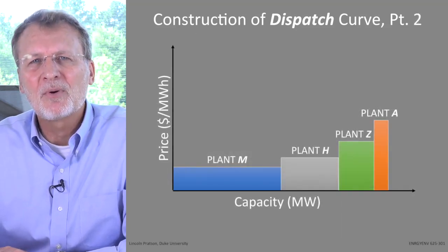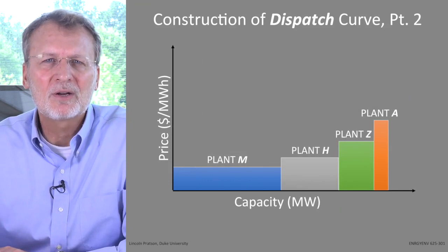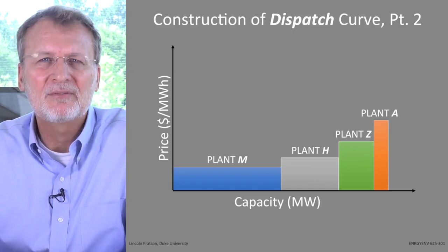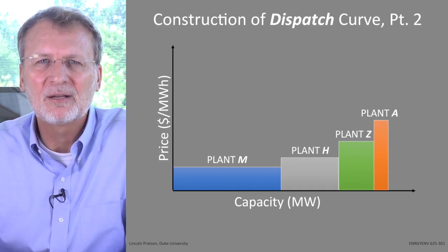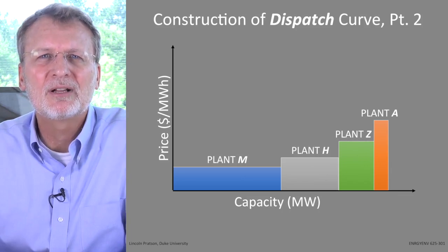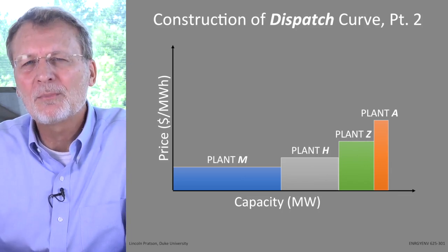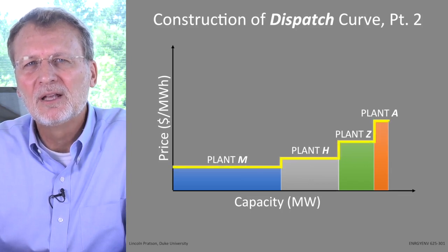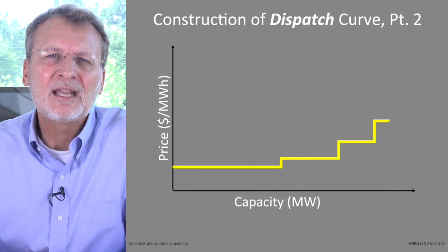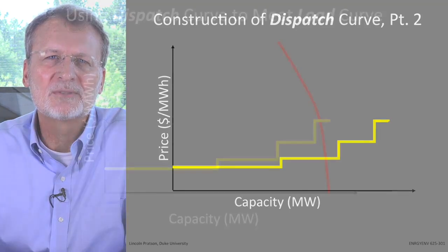The system operator arranges the generator squares from lowest to highest price. So while the width of any square, or the offered power capacity of any generator, varies in this lineup, the height of the square, or the price that the generator is willing to generate electricity for, rises monotonically from left to right. This result then is a supply curve in that it indicates the cumulative generation capacity available during the day at each level of offered prices.